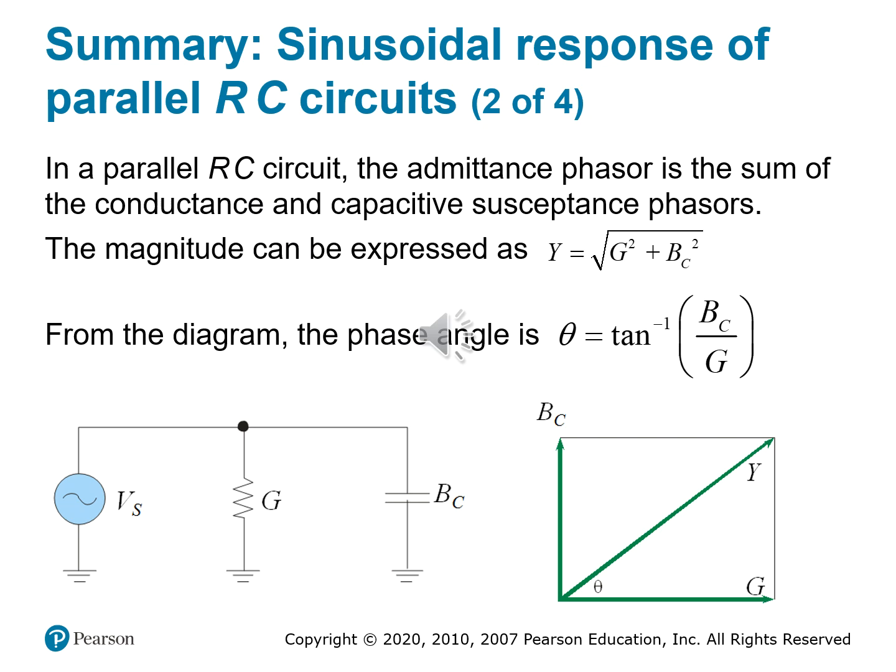And here's where things get especially interesting. A large susceptance means a strong capacitive presence, which pulls the phase angle closer to plus 90 degrees. That's the opposite of what we saw in the RL circuits, where inductive reactance pulled the angle down. And this is important because the triangle gives us, again, a visual geometric way to think about phase behavior.